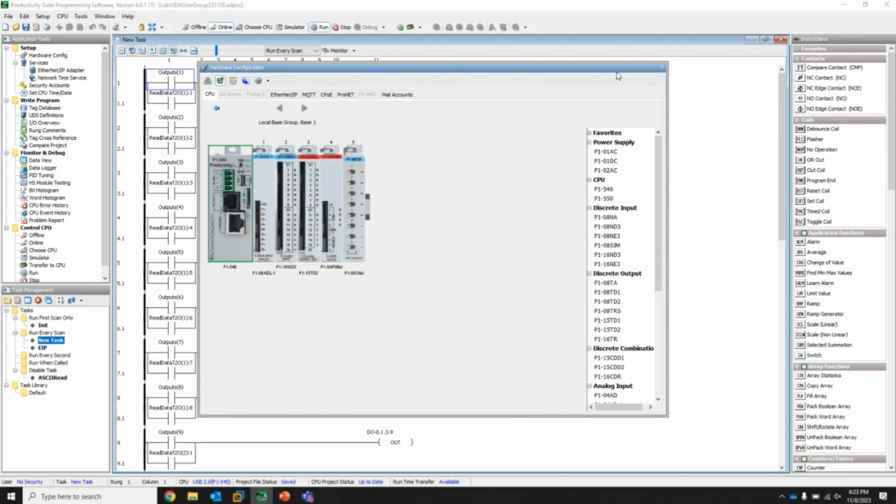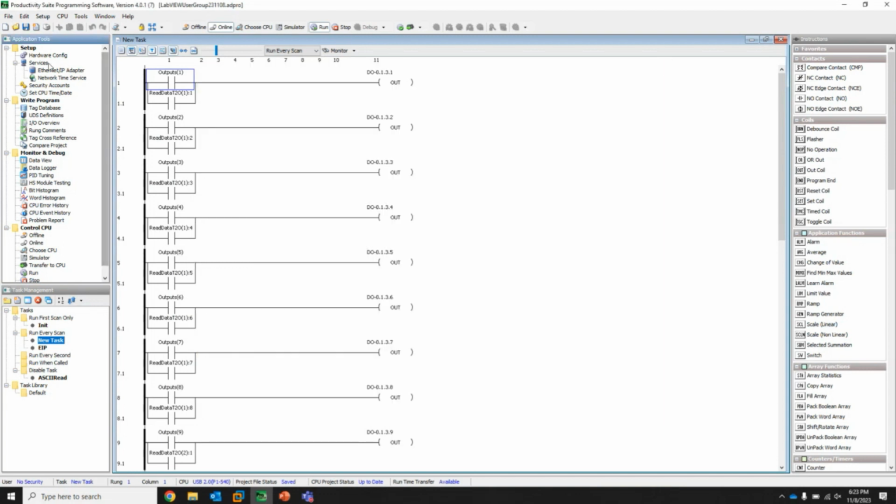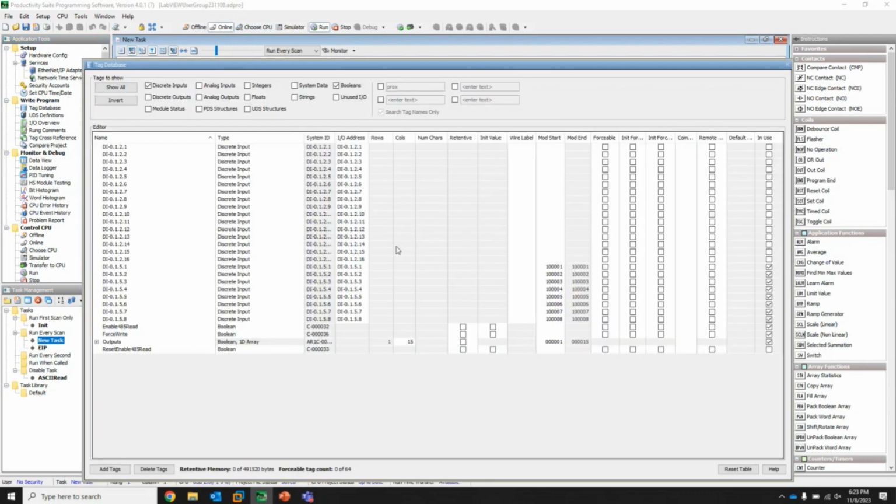And then the other one that's important for Modbus is that you actually have addresses that exist. So with the Productivity, you're able to map anything to really almost any Modbus address. Discrete inputs are going to go to the discrete input types of Modbus registers. Analog inputs will go to the input registers. And then you have the option with coils and holding registers for writing down U32 data or binary data, bit stuff.